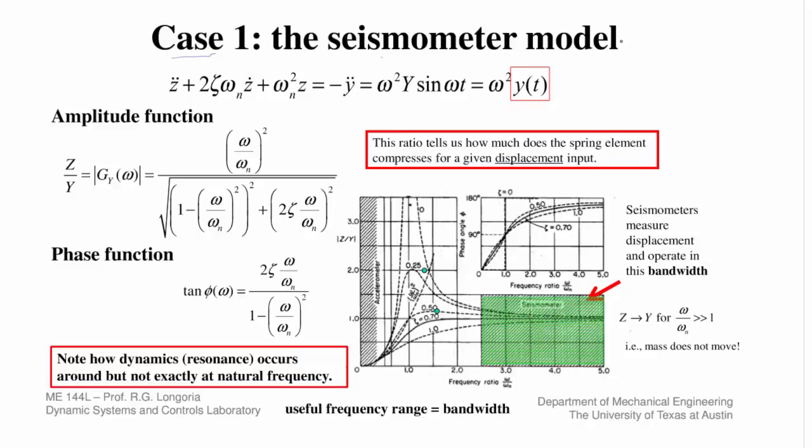So take the original equation and rewrite it so that we introduce the parameters that I hope you're familiar with by now, which is the damping ratio and the natural frequency. Basically, I've divided by the mass, right? And now on the right hand side here, note that I've got the forcing frequency in here squared, and then y of t is the input of the base.